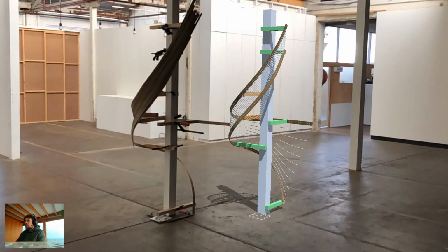So with this project, it was about trying to use mixed reality as a kind of guide for steam bending timber parts. We would have a hologram showing us the shape of a piece of timber that would be part of the building, and maybe a hologram showing us roughly how to set out some formwork for that shape. You would then place the formwork where you saw it on the hologram and bend a piece of timber until it was the same shape as the hologram.